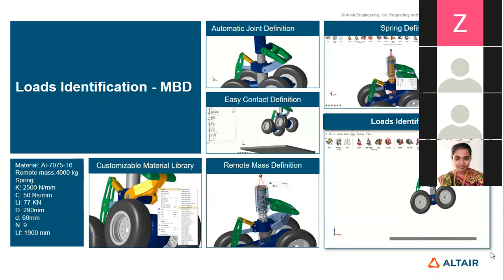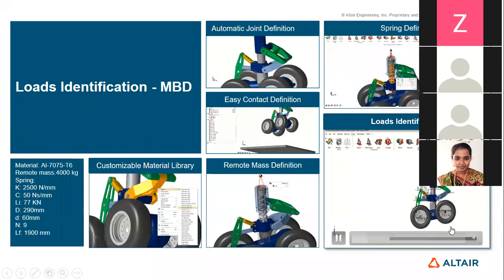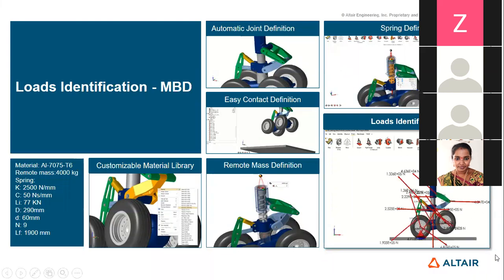So basically those ribs are the optimized design. Optimized design means it depends on what type of loading the component is getting. To bear that load, those ribs are sufficient. You don't need to put the whole plate over there. So that is the topology optimization. In this first section, we have covered what type of loading we are getting. If you know about the loading, that is very good. If you don't know about the loading, then we have to do some kind of iterations.